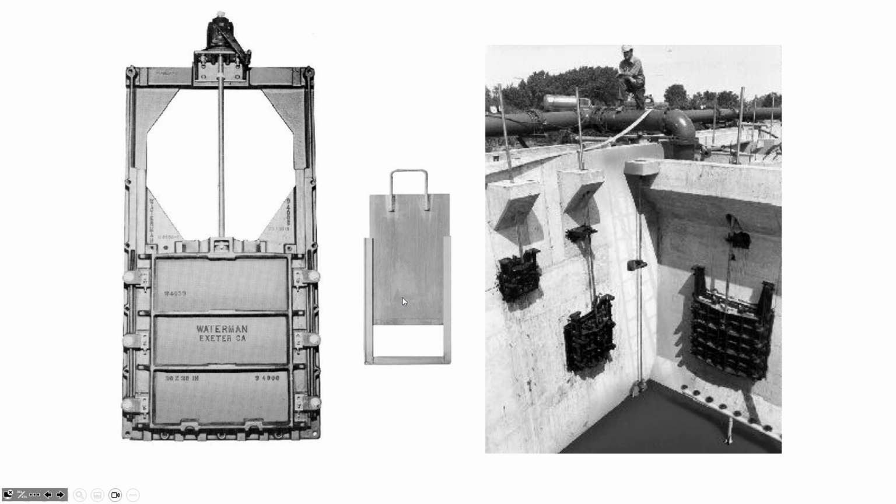You can't turn up bacteria. So we have to feed the bacteria that break down biological waste at a more constant rate. And so flow equalization basins will take the incoming sewage during peak times and store it briefly, and then meter it into the plant overnight when the flow rate into the plant would otherwise be kind of low.